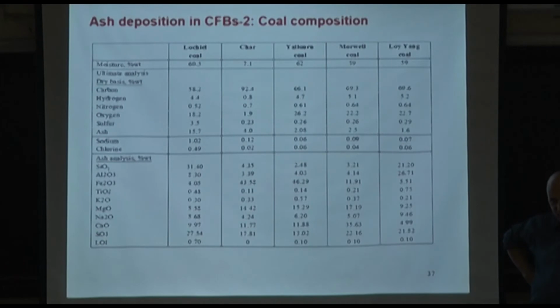But the important thing is to know how it is actually done, because you can get all sorts of different results. So it's best done in a lab where they have used the X-ray fluorescence unit day in, day out, but it is also good to ask them, because not all coals can be equally efficiently or correctly analyzed by X-ray fluorescence.